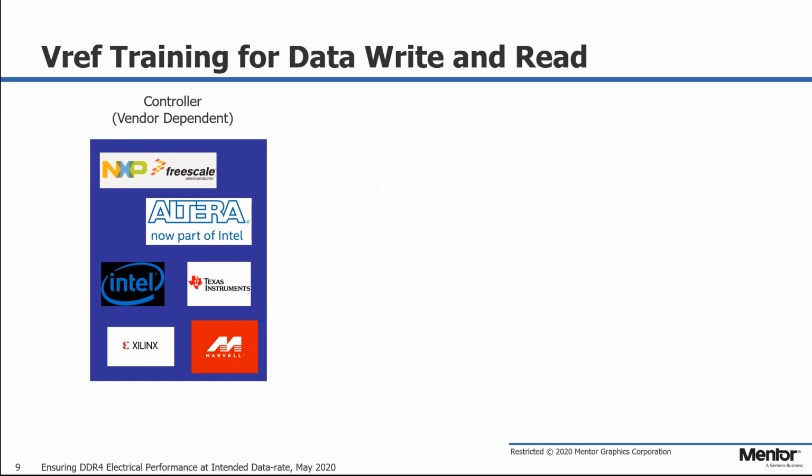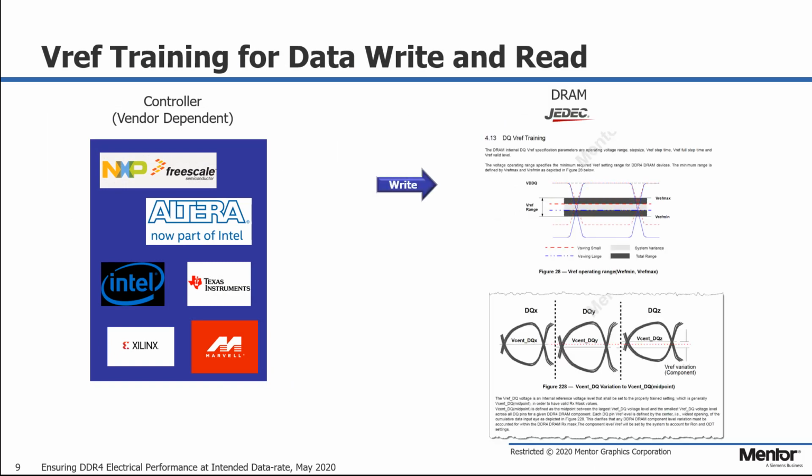During the write cycle, the algorithm for the VREF training is specified in the JEDEC spec as shown here. During the read cycle, you will need to know how the VREF training is done by the particular vendor. I'll show you in the demo how those options are set in the DDRx Wizard in HyperLynx. It is important that proper VREF is considered so that you are making timing and SI measurements at the correct voltage level.